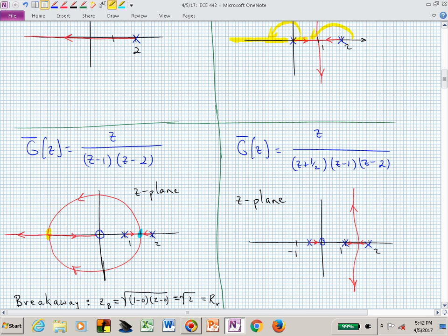What's my pole zero excess? So where are my zeros at? How many zeros at infinity do I have? I have as many as I have a pole zero excess. So I now have 2 zeros at infinity. They're going to be going at 180 degrees divided by 2, or plus and minus 90 in this case.